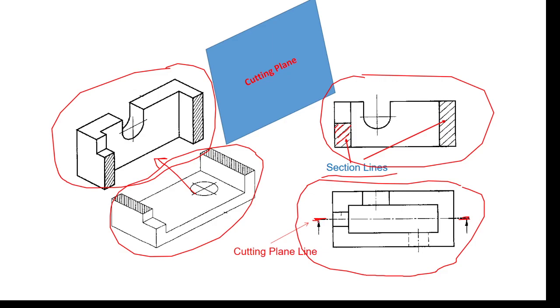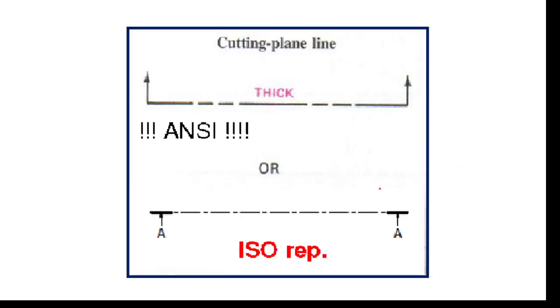It is to be considered as if it were used for cutting, for outputting the view directed toward the frontal picture plane. So these arrows, by their directions, imply that the corresponding sectional view is the front view, the sectional front view. At this point, I want to highlight that the cutting plane line format is completely different in accordance with ANSI.